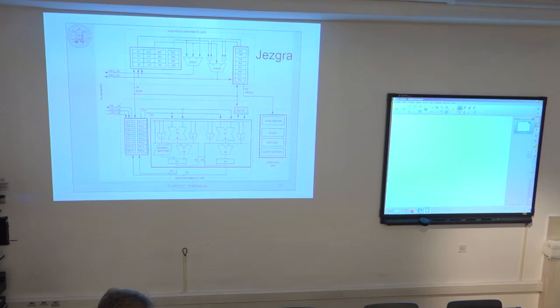But nevertheless, to solve this, you might have cache memory that is multi-ported, that has multiple blocks. One block for, let's say, the first data space, another block of cache memory for another data space, and finally another block of cache memory for program space. In this case, this multi-ported cache can supply all 3 output values, data from the first space, data from another address, instruction from the third address, in the same cycle, if they are stored in the cache.